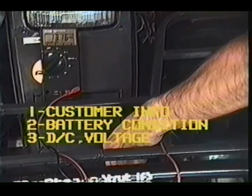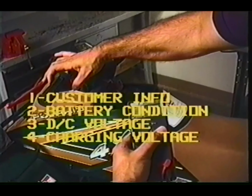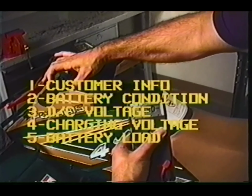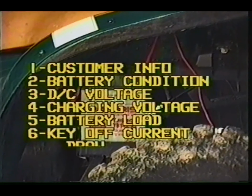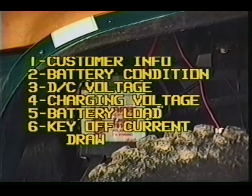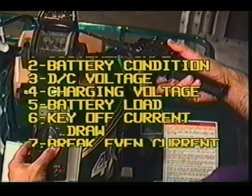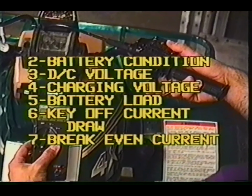Check the battery voltage. A fully charged battery should read 12.4 volts. Start the engine and increase RPM. Battery voltage should increase to around 14.5 volts. Load test the battery to check reserve capacity. If the battery is discharging in storage, check for current draw with the key off. Check the current draw with the engine running and record the break-even RPM for future reference and comparison.